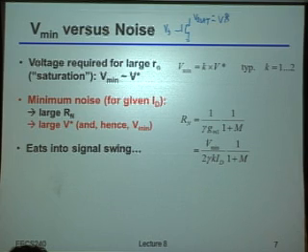But to fix that, in somewhat of a hack way, but it'll work, we're going to define a new parameter that I'm going to call Vmin. Okay? Vmin is the minimum voltage I need across the transistor to make sure it has a sufficiently high output impedance. And by analogy, I can always say that Vmin is just some arbitrary k times V star, right?